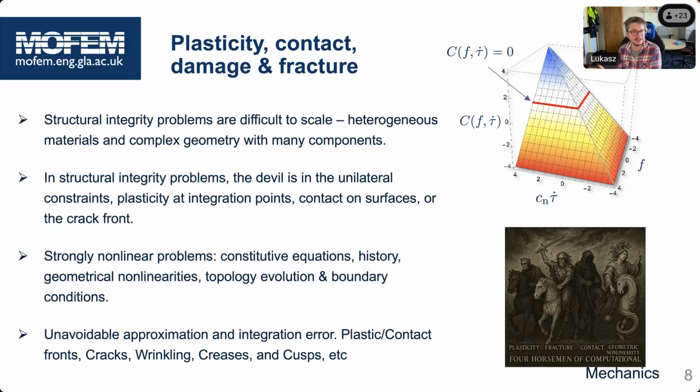In addition, you have to remember that we have to keep the information from the constitutive equations. When you deal with solids, they remember what you have done to them. Fluids forget, so this adds another dimension of difficulty, because you have to carry the history. So the arbitrary Lagrangian-Eulerian formulation becomes even trickier in those cases, and mixed elements are again the way to deal with it.